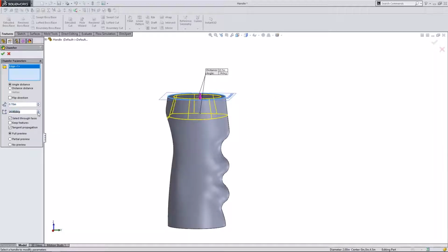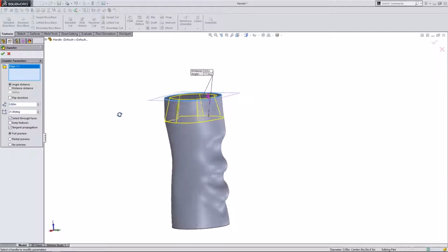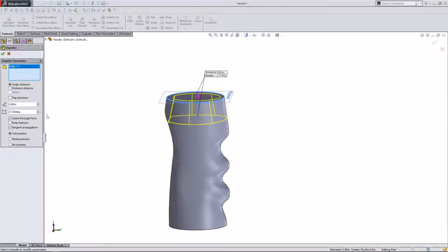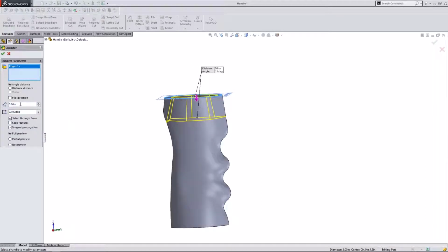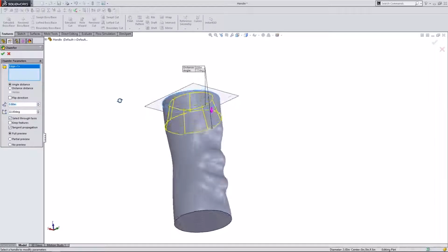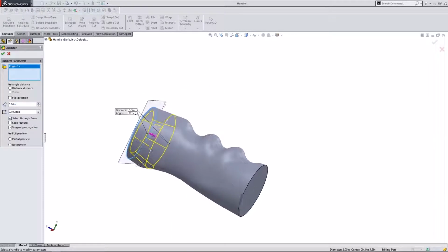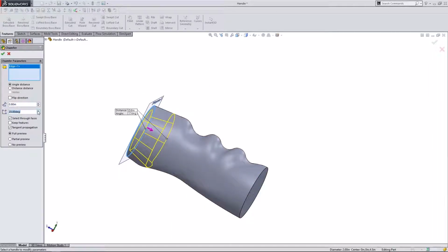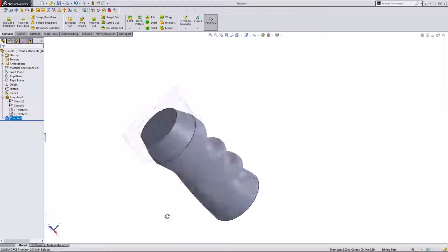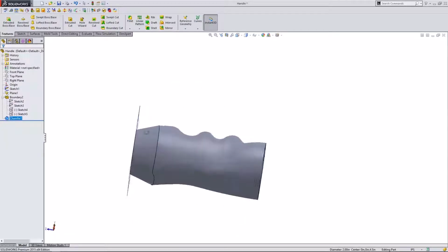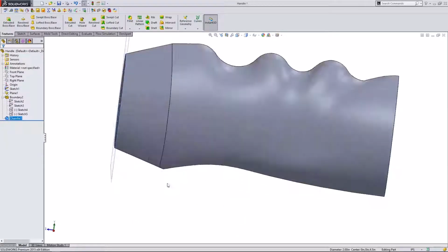See, the angle that you use when you make a chamfer and the distance are commensurate with each other. So you can keep changing the angle, and you can make this distance longer and longer depending on your part geometry. But there will come a point where it'll yield and it won't work. So I'm going to try to bump this up as much as I can. I'm going to change it to 24, hit OK. And so we're kind of hacking at this shape more and more.